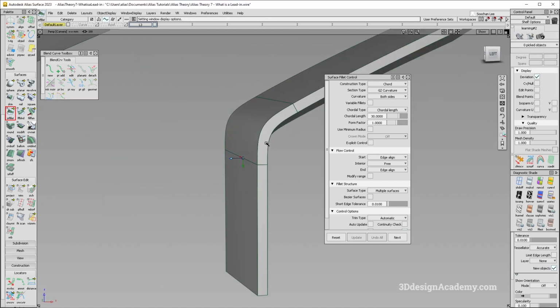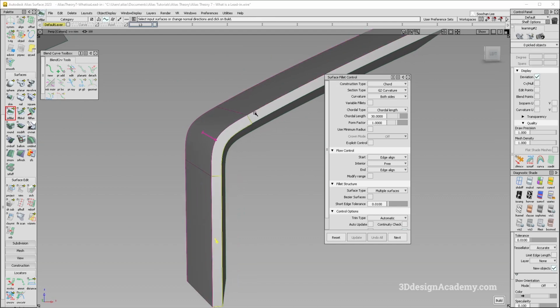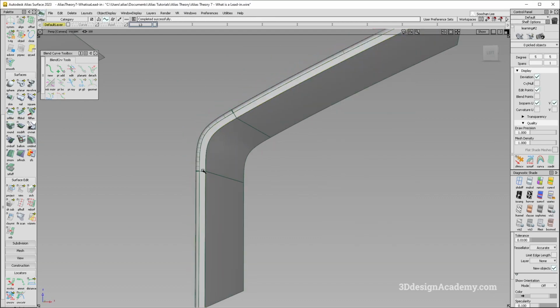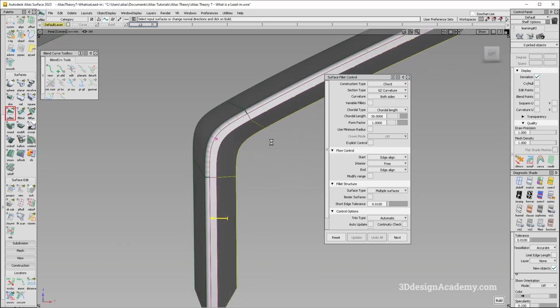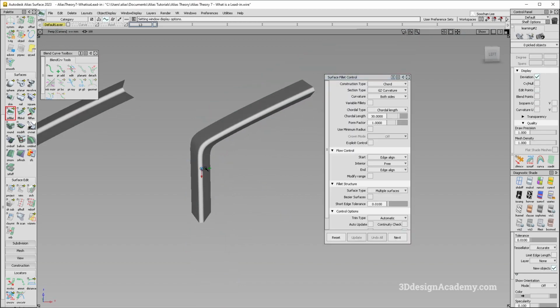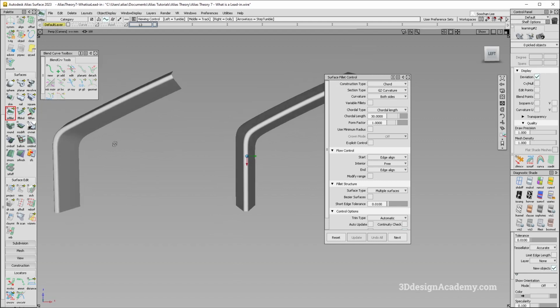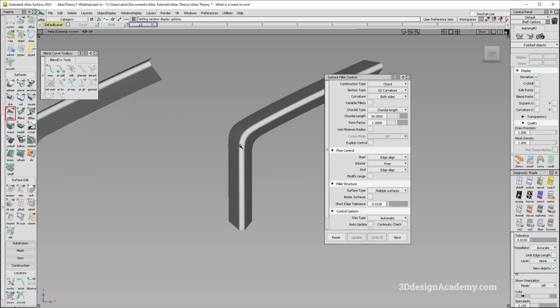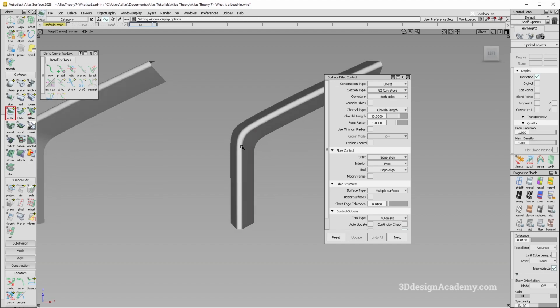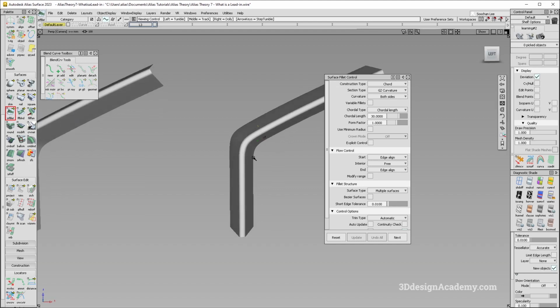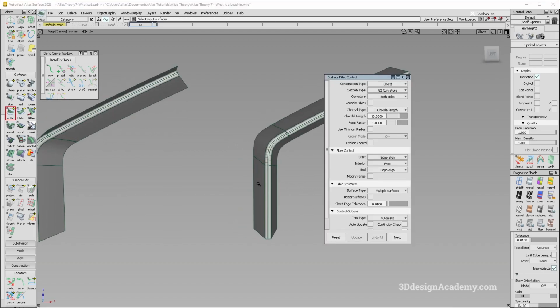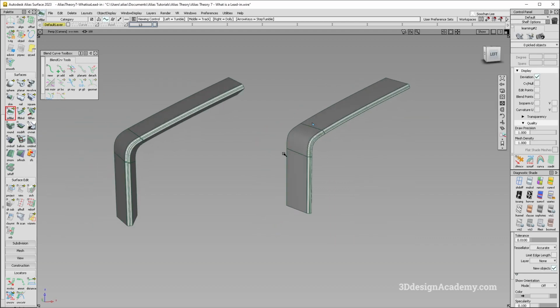Now let's do the same thing where the surface has a little more lead-in, and let's see how that looks. I'm just going to put the same quarter fillet of 30, and do edge align over here. If you see this one, I don't see that transition there. I don't see that weird kink that feels like it's going up and down. It just looks like it's transitioning nicely to the other primary surface. So this is another way lead-in is very critical for building good surfaces.